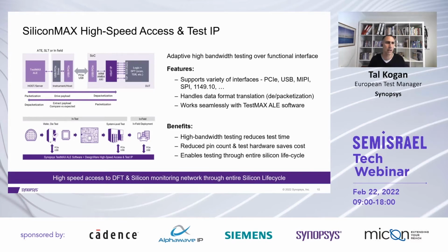Again, let's assume you have your tester here, and through that, you drive the functional interfaces of your USB or PCIe into the SoC, and data is written through your AXI bus into the IP, which actually translates that into scan data, driving at the end those internal scan chains that we still have, right?